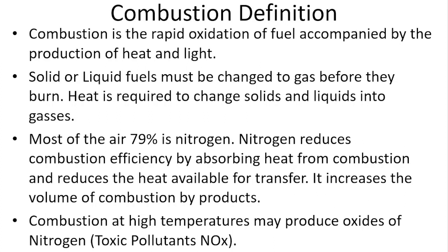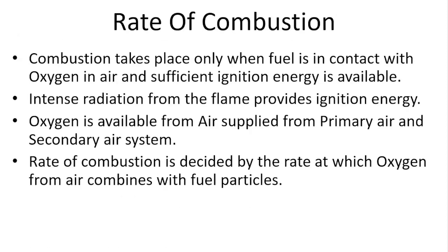Now what is combustion? Combustion definition. Combustion is the rapid oxidation of fuel accompanied by the production of heat and light. Solid or liquid fuels must be changed to gas before they burn. Heat is required to change the solids and liquids into gases. Most of the air, 79%, is nitrogen. Nitrogen reduces combustion efficiency by absorbing heat from combustion and reduces the heat available for transfer. It increases the volume of combustion byproducts. Combustion at high temperatures may produce oxides of nitrogen, which are toxic pollutants.